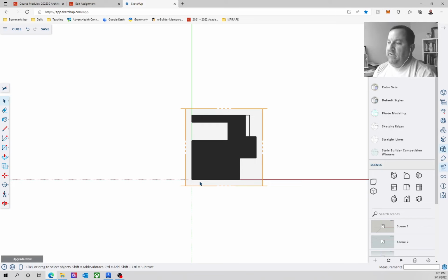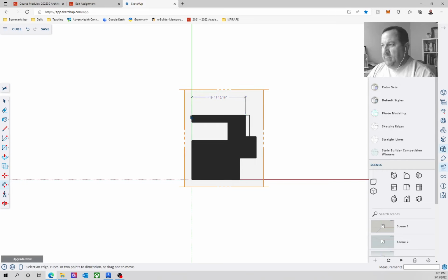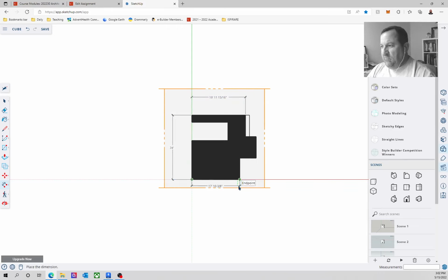Well, we'll see. But anyway, now that we have the model cut, and again, you're not physically cutting your model, you're just going to draw an imaginary line at that plane, the cut plane, and then you're going to measure those elements and draw that in plan. So for me, I have this. I'm going to dimension it or measure it so that I can recreate the drawing in Revit. So I'm choosing the dimension tool, and I'm going to pick just the larger dimensions just to get started with. And I'm not looking for 1/16 of an inch accuracy. I'm just looking for some overall numbers.